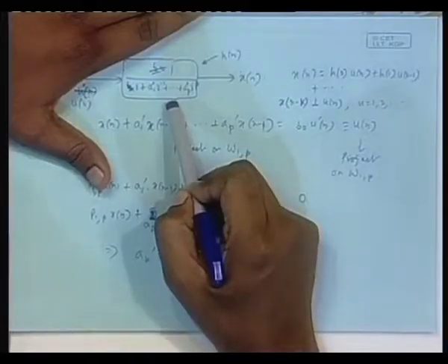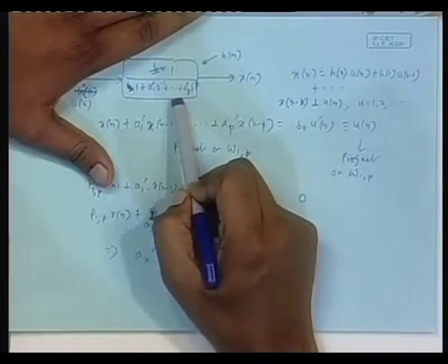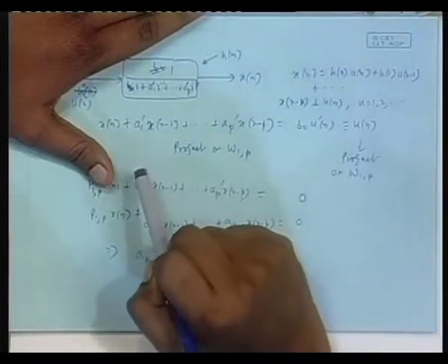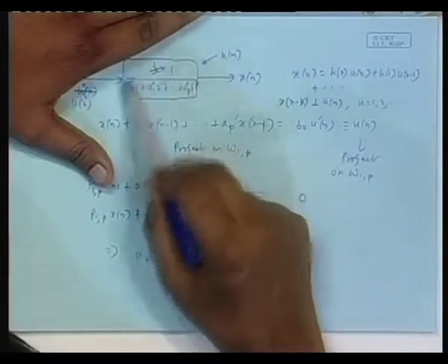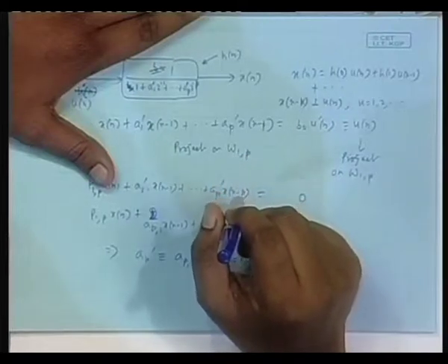So this part is a linear predictor polynomial, but this has now gone to the denominator. That means the roots here, which are poles, are lying within the unit circle. That is guaranteed from linear prediction theory, which I proved yesterday. That means this model is such that it has all poles lying within the unit circle in the Z plane, which means it is causal and stable.